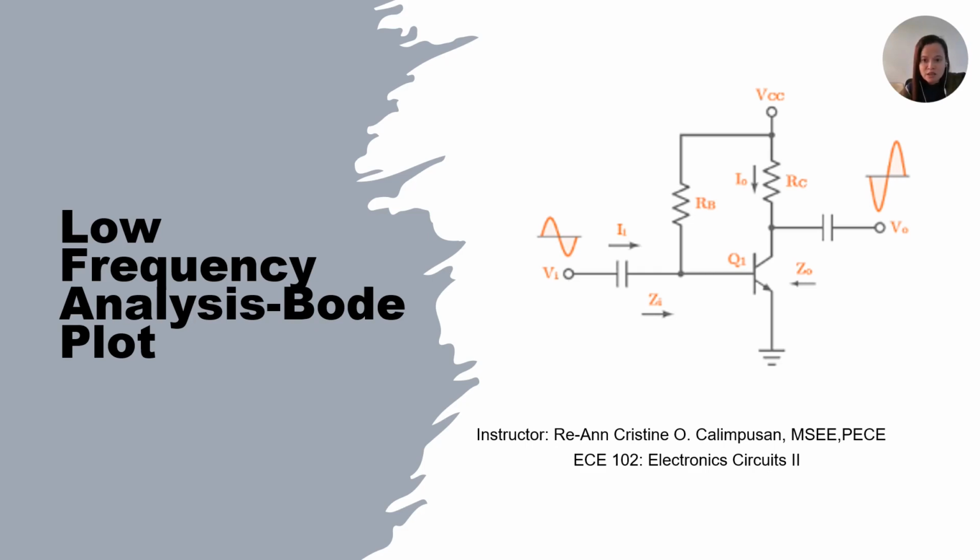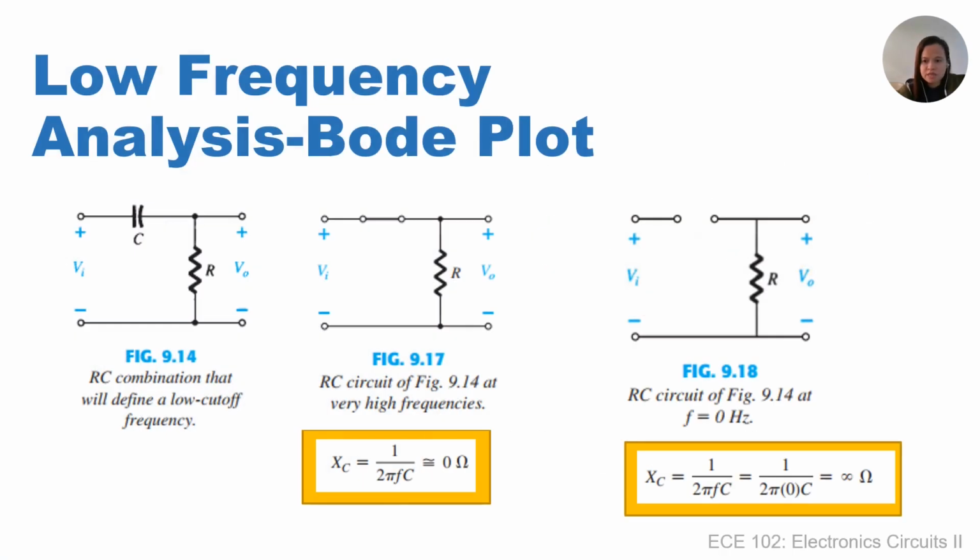So when the output voltage with respect to the input reaches 0.707, that is what we call the cutoff frequency. Once the cutoff frequency due to each of these capacitors is determined, they can be compared to establish which resistive elements and capacitive elements will determine the cutoff frequency. So that is our goal: we will find the value of the resistor, the capacitor, and the cutoff frequency.